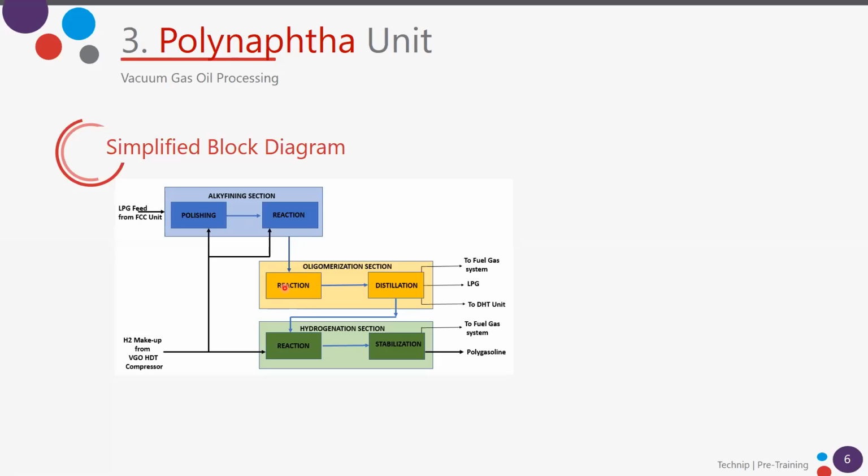Yeah. So one step you increase it, and the subsequent step is to decrease it. So one step is you increase the size of the olefins. Yes. Always talking about olefins, and then you hydrogenate part of the olefins to reduce it to the required level. Yes, you reduce the olefin content because of the specification of the gasoline pool.